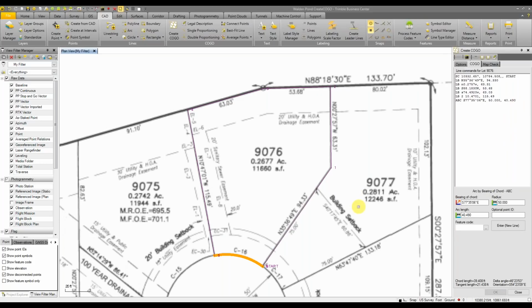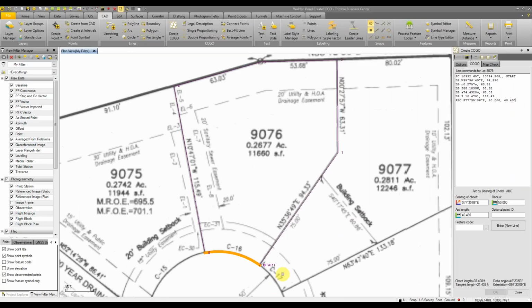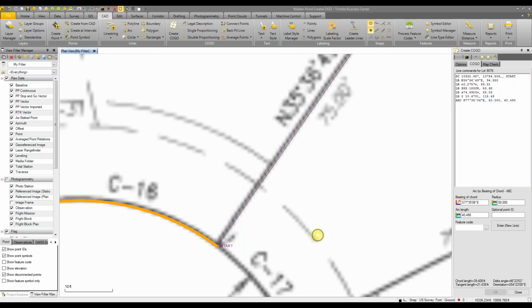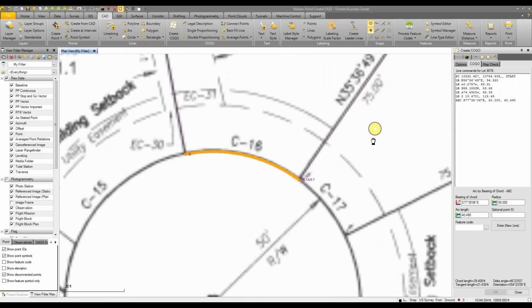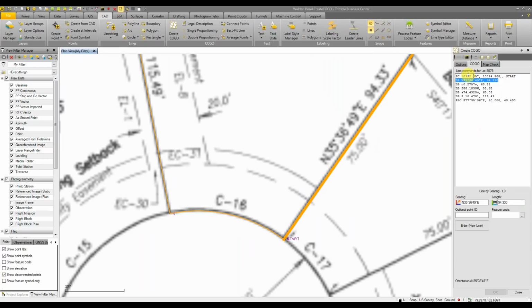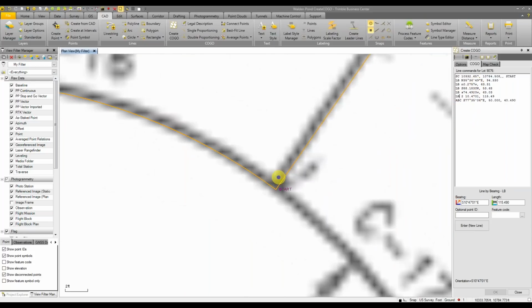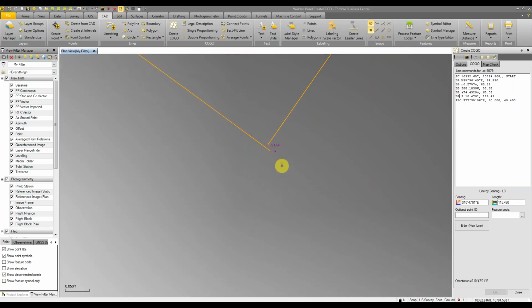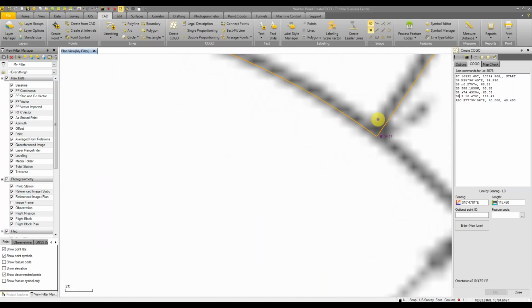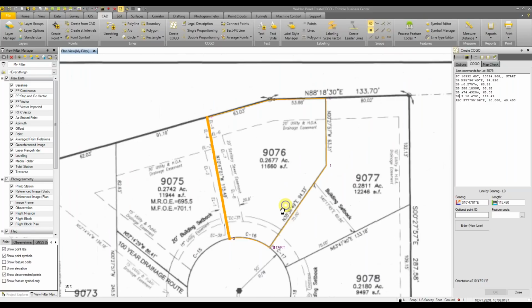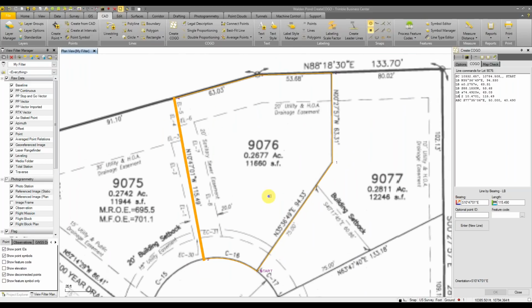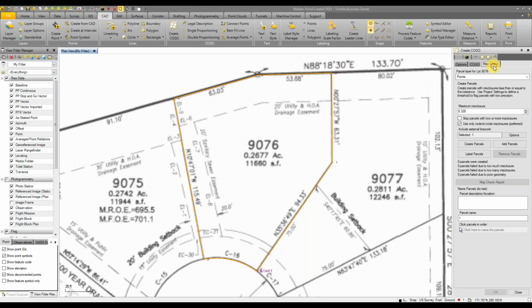Excellent. Is there any misclosure there, Matt? Can you zoom in? Yeah, let's zoom in and take a look, shall we? If you click on the line segment, it'll highlight the line in the text that is related to that segment. Also, if you click on the line of text, it will highlight the line segment that is on the plan view, so the two of them work quite nicely together like that. If we zoom in, there's some misclosure there. TBC is the next workflow I'm going to go through. Actually, we'll quantify that misclosure as well as the direction of it.